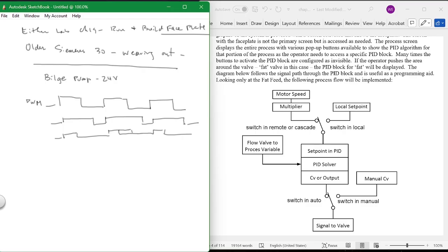So you put a potentiometer on the valve and you turn, and if it doesn't respond, what do you do? You stick in manual, because you want to stay where you're at, and you don't want the integral of the error term to start building up. And what else do you do? You tell an operator to get a maintenance person to go fix the linkage. And when they get it fixed, then you go back into auto, and you're back in business.